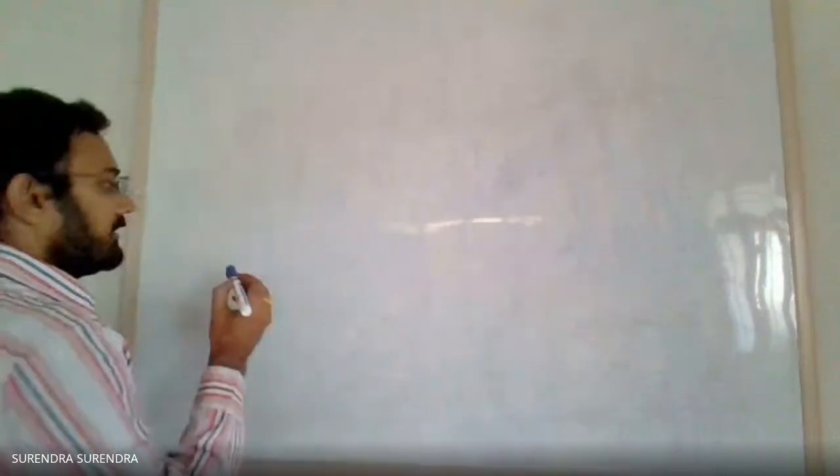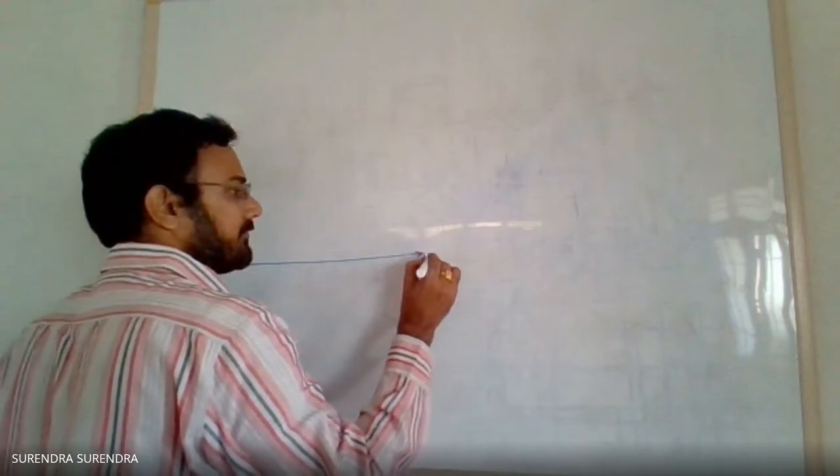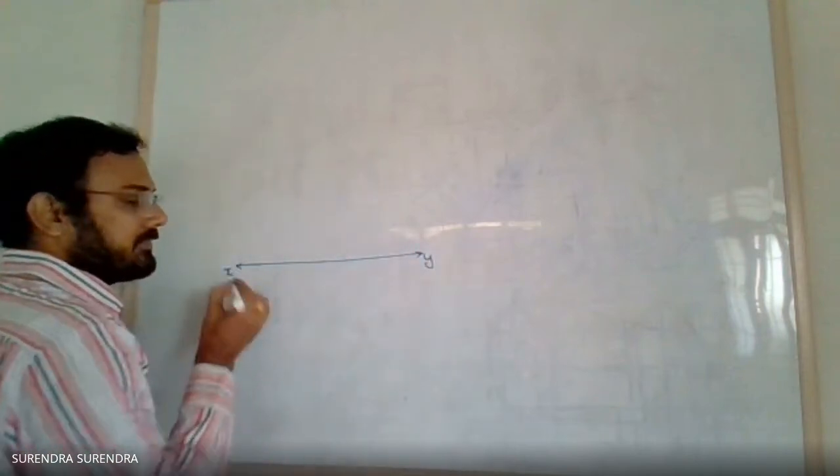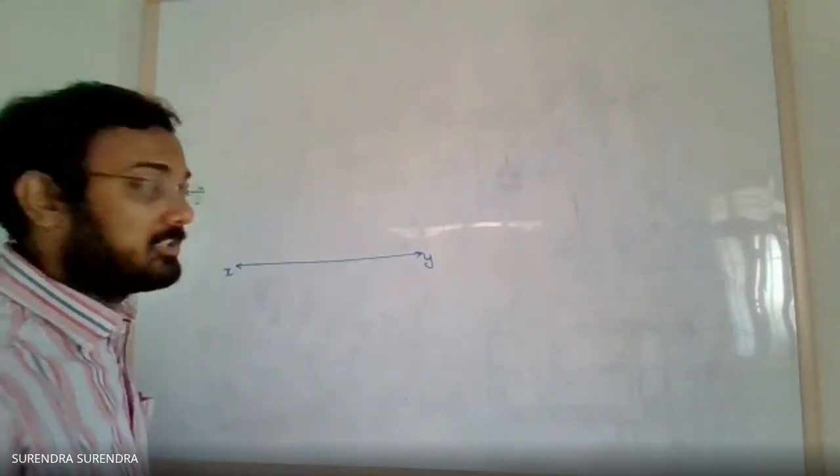A square pyramid of base 25 mm and altitude 50 mm rests on its base on HP with two of the base edges parallel to VP. It is cut by a section plane bisecting the axis, inclined at 30 degrees to the base. Draw the development of the lateral surface of the lower part of the cut pyramid. So first draw the pyramid in the given position, with the XY line.